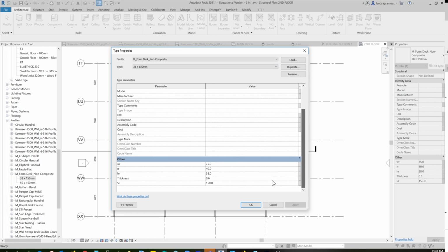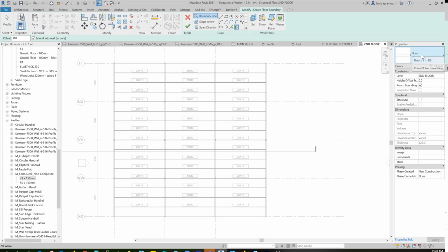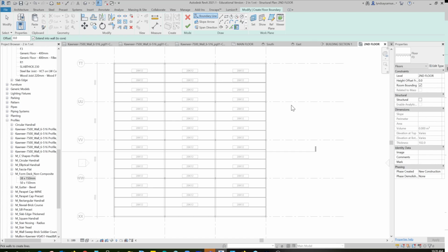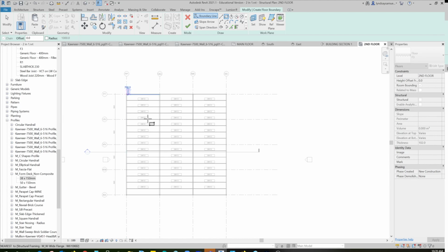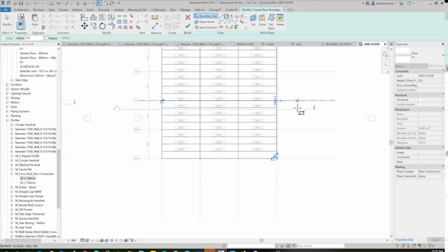And then you have to go down into here and change the HR to 38, so that when you create your floor and you call it whatever, there's my F3, when you're in there you select the metal deck layer and you tell it to use this profile, 38. Okay, so now I've got the assembly created, and all I really need to do to start off is go from the grid line intersection of that column down to here. Later I'll put holes in this for stairwells and things, but this is a good start.